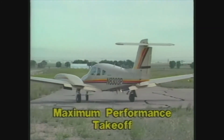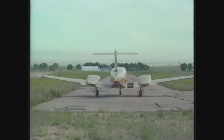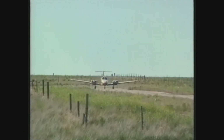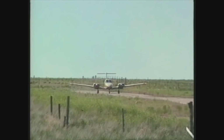If a maximum performance takeoff is required, set the flaps as recommended by the manufacturer and follow the procedures in the pilot's operating handbook. Make sure you use all of the available runway. Apply full power before releasing the brakes.